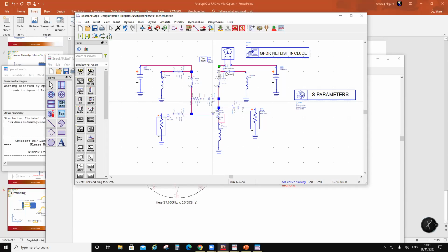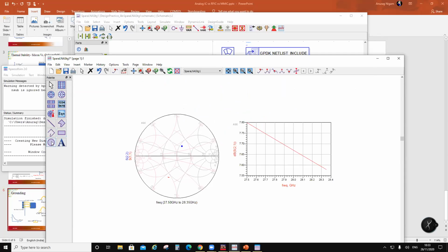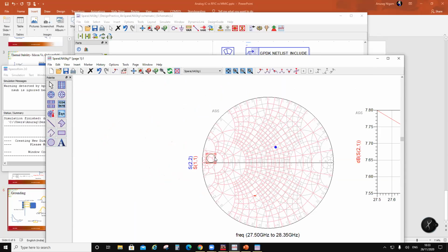So somebody would question, oh, 10 picofarad and then 0.1 microfarad, so what is the need for 10 picofarad? You have 0.1 microfarad in parallel. Now, your equivalent series resistance has gone down if you put two capacitors here. Okay, so what is going to happen? The short, which was here, okay, of course I cannot draw very clearly, the short which was here because of a capacitor is going to be closer to a short. Okay, so the good short has to be created.